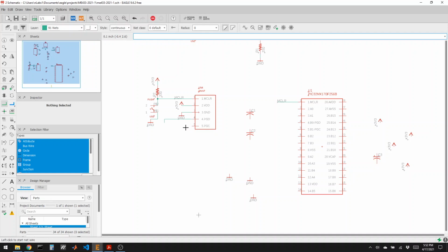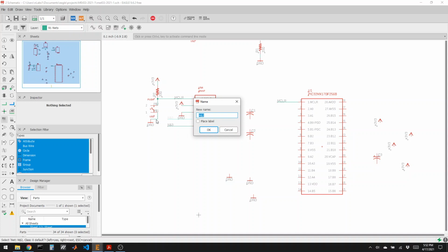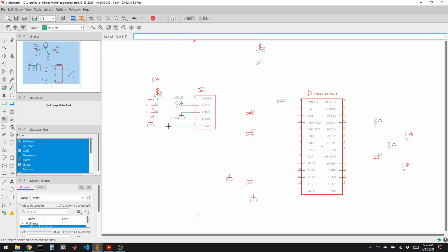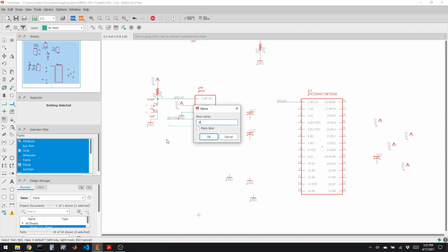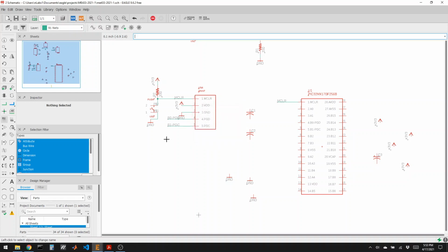And then we have our two programming pins, PGD and PGC. And I've chosen B0 and B1 for those, but we're gonna have to double up on those functions. So I'm gonna remember to give them their full names. PGD, we're gonna call B0-PGD. And PGC is going to be B1-PGC. We'll make those connections.